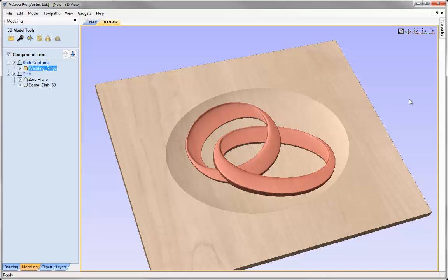But what I want to show you here is a little bit more of an advanced concept that we can use to do this for us. Now one other good tip to show you at this point though is that sometimes visually it's not obvious that anything in a dish is sticking out above the edge, and that can cause you real problems when you come to machine it, because you'll end up with a lip around the edge of your part. Instead of having this nice transition here, you'd end up with a vertical edge around your dish.